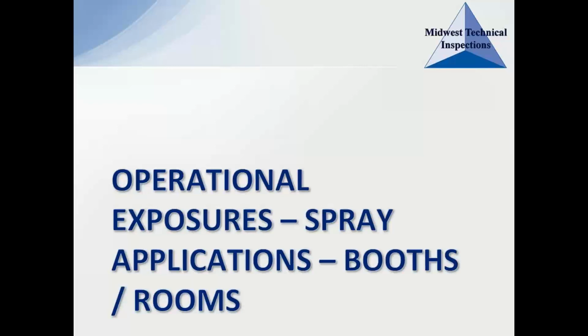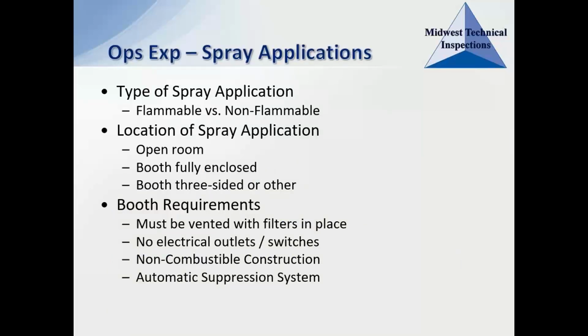Spray applications in booths or rooms. So just like everything else, we need to identify the types of sprays that they're doing, because there's a huge difference between a flammable spray and a non-flammable spray. With both of these, you're vaporizing this material, so it's becoming more combustible just in the fact that it's vaporized.